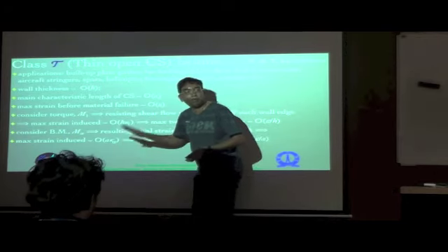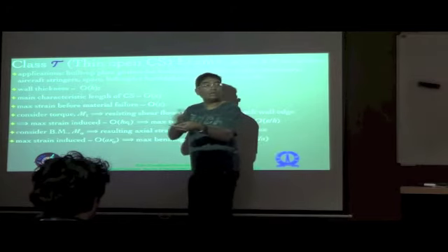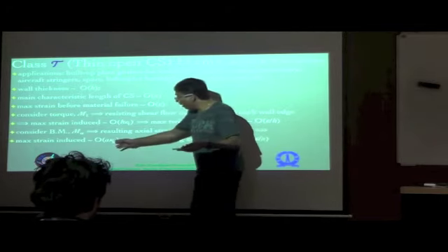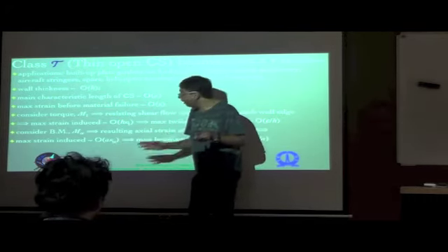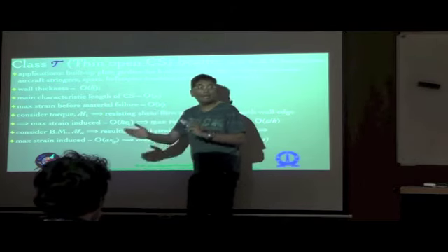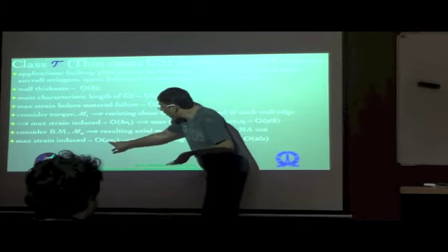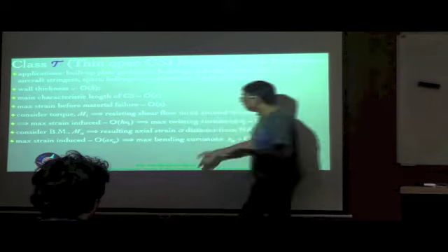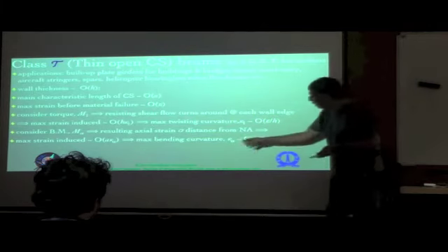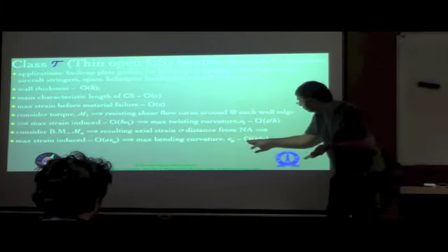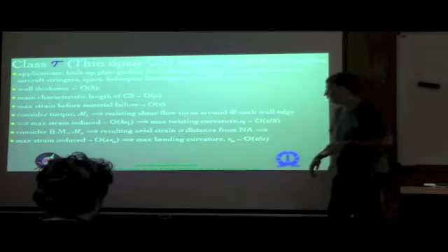Here the Greek subscript alpha refers to the smaller dimensions in the beam. The larger dimension is 1, which is along the length of the beam. Alpha, beta, gamma, whatever Greek subscripts that I might use, unless otherwise specified, can vary between 2 and 3. That is within the cross-sectional coordinates, that is x2 and x3. So here I can estimate kappa 2 and kappa 3 because this is of the order of epsilon. Therefore, the maximum bending curvature that can be reached at failure is basically of the order of epsilon divided by a, right, in both the directions, kappa 2 and kappa 3.